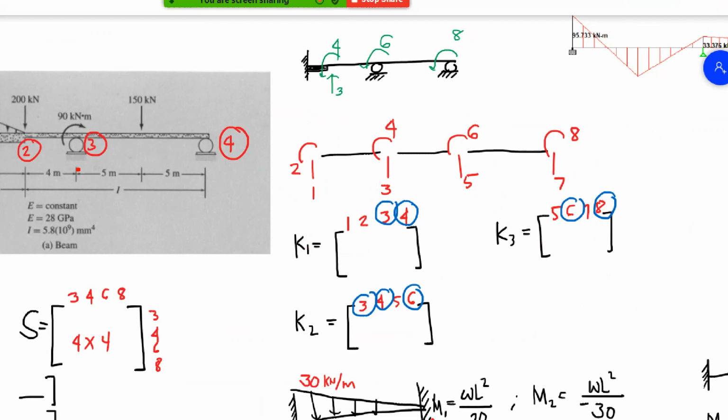And as you notice, since node 2 is just a junction at which inertia changes, the degrees of freedom here will be 2, because at this location your continuous beam has a vertical displacement, which corresponds to degree of freedom 3, and it also has a rotation, which corresponds to degree of freedom 4.